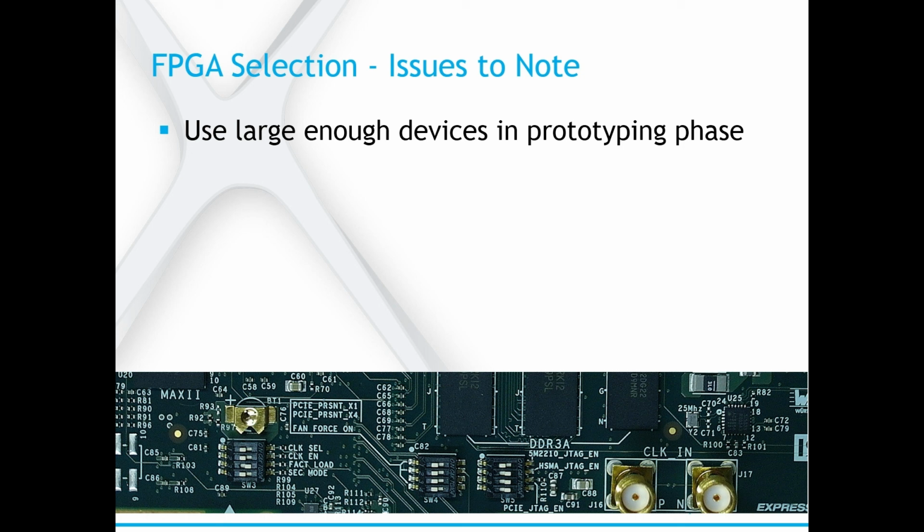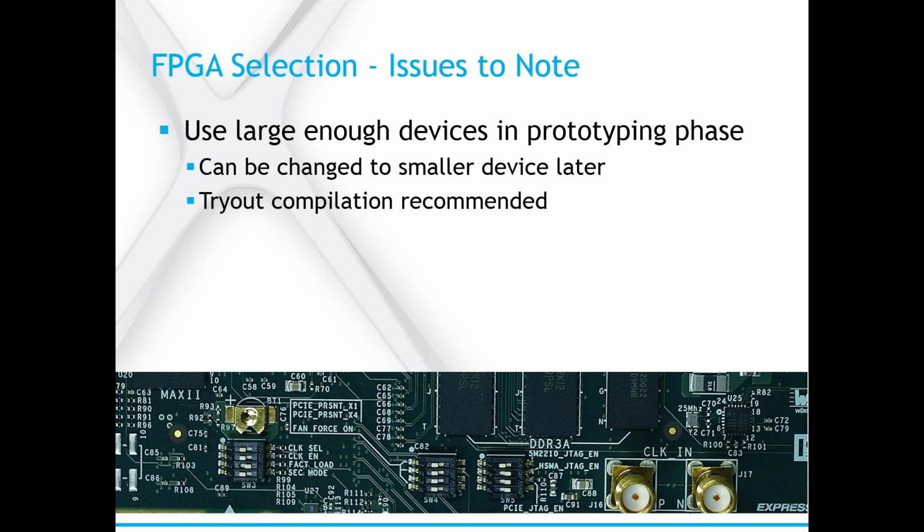FPGA devices in the same package are typically pin compatible, which makes it possible to change the FPGA device to a smaller one later if the resource consumption of the final logic is low enough. Tryout compilations are always recommended before the final device selection.